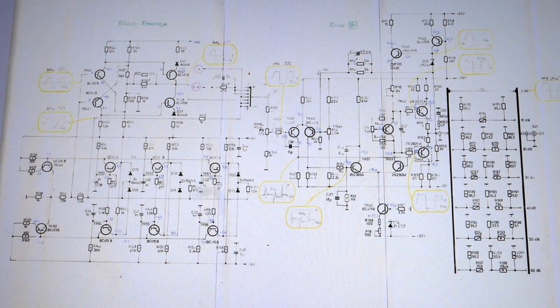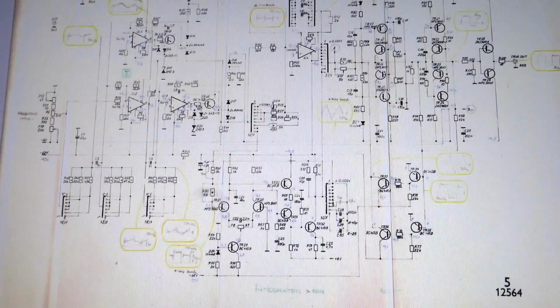And of course you can also turn anything into a sine wave using several succeeding low-pass filters, but this would also be quite frequency dependent. And this triangle wave to sine wave converter has to be frequency independent. But anyway, the problem is not on this page. Let's go back to the other one.